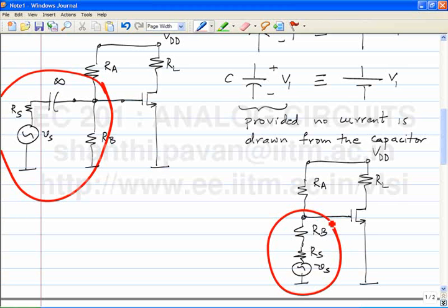problem. One is that, please note that DC current flows through the source. In this chart here, DC current flows through the source, which is again not an option for many sources. For example, this microphone here is what is called a condenser mic. Two plates of a capacitor, and when I speak into the mic, one of the plates vibrates, changing the capacitance between the two plates. And therefore it turns out that it is not possible to have DC current pass through the source. That's just the way the source is built.